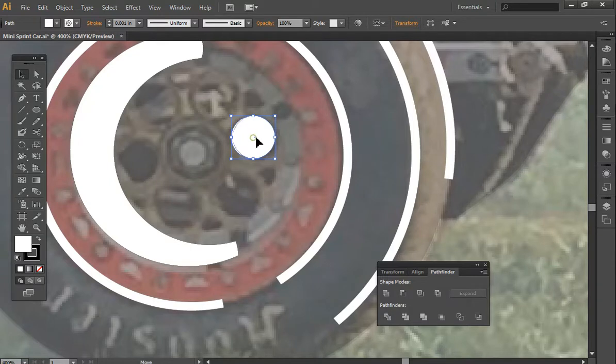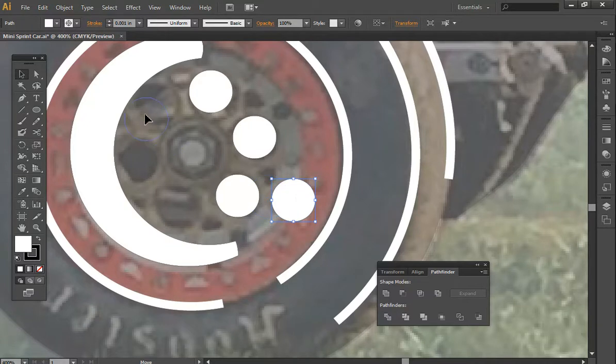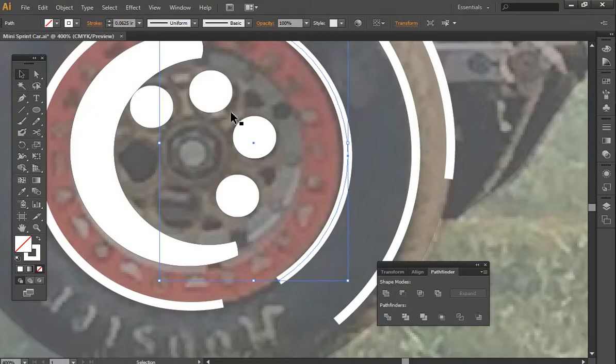Okay, draw that with the ellipse tool, copy and paste it. We want to have pretty much the same diameter on all these. We want to make sure the spacing is not too close. So we're looking at this, that's 0.0625. So we're at 0.1, maybe 0.125 in between here, which, with my experience, is plenty enough room.